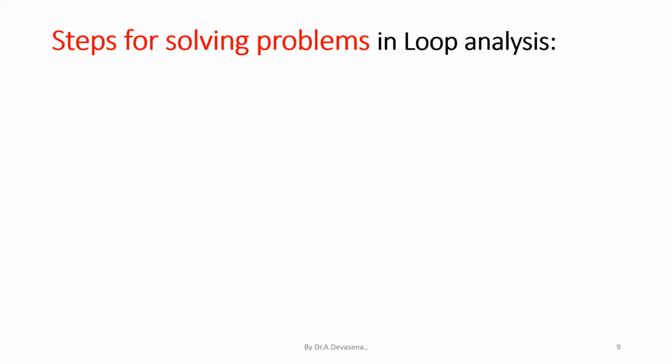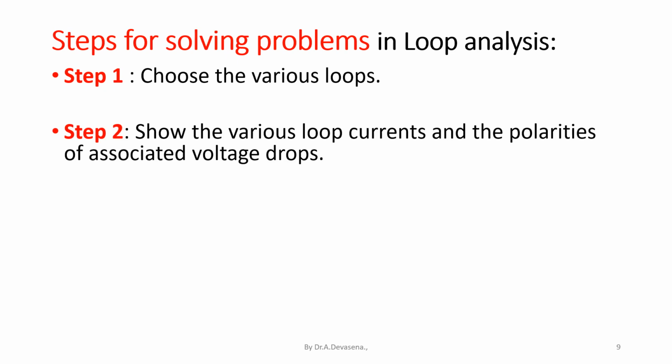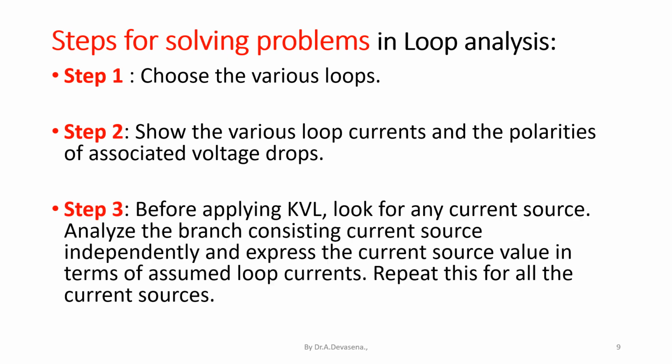So far we have discussed the theory related to loop analysis. Let us start discussing the steps for solving problems using loop analysis. Step 1. Choose the various loops. Step 2. Show the various loop currents and the polarities of associated voltage drops.